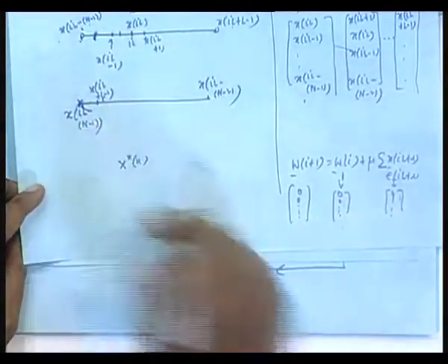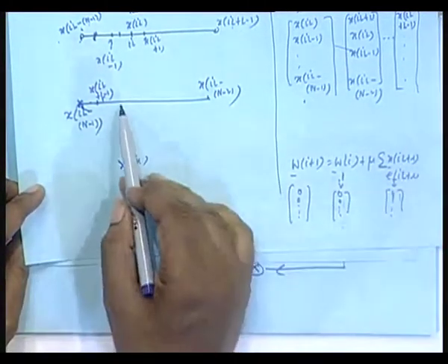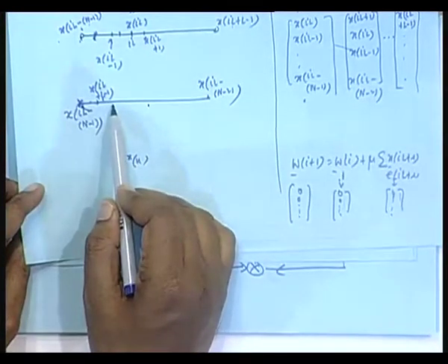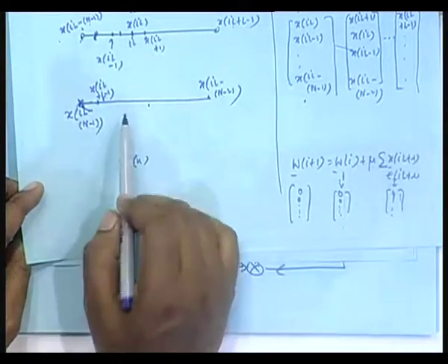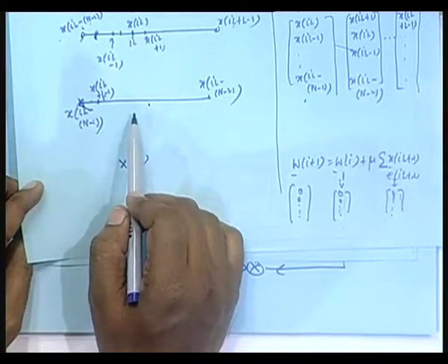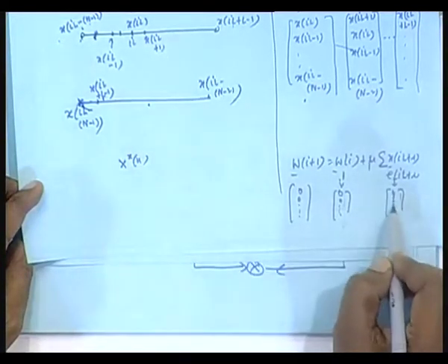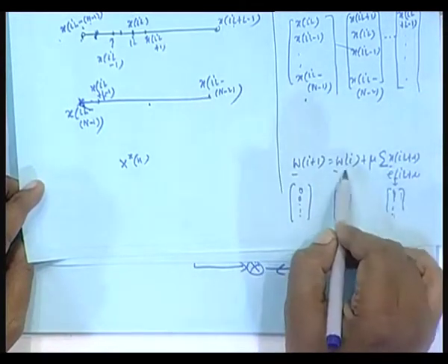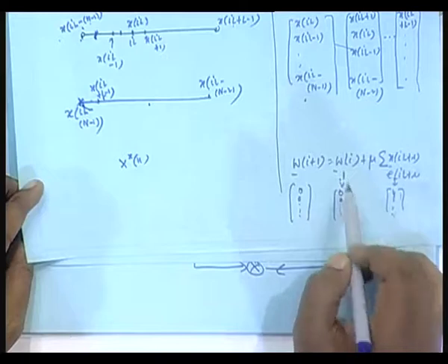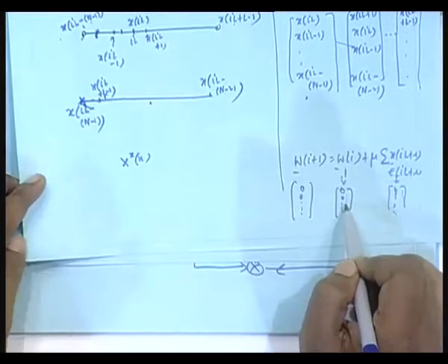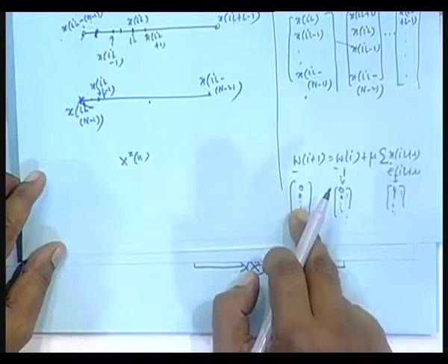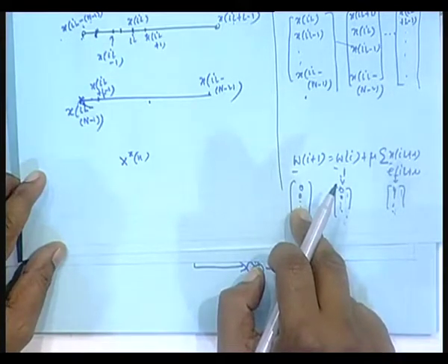So, in the weight update part, to carry this out, I told you that I will take circular convolution between this and this, but I need only the first n, the remaining ones I do not need, but I put zeros there. So, that this 0 vector comes below. And suppose in the previous block the weights have been updated like that, the last L minus 1 entries are 0. So, if you do the update, this also will have 0, isn't it?